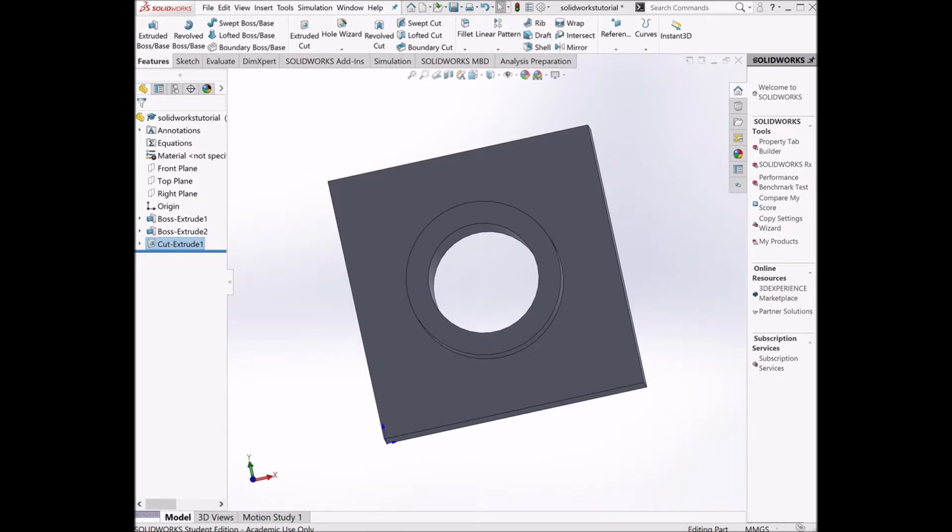Now, SolidWorks, this tutorial starts off by adding the fillets, the bigger fillets, the 5mm fillets. I recommend you always start with the smallest fillets first and then make your bigger fillets. So I'm going to skip to the next step and we're going to come back to this page.